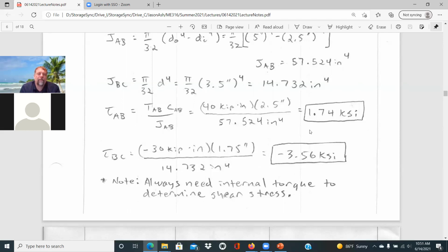How do we account for that, in that materials fail differently in terms of how they're loaded? And so the way your book manages that, they don't discuss failure theories until later on, is instead of using a uniaxial shear stress, they define shear yield stress. So you're able to use that number for calculations if you're needing to find factors of safety.